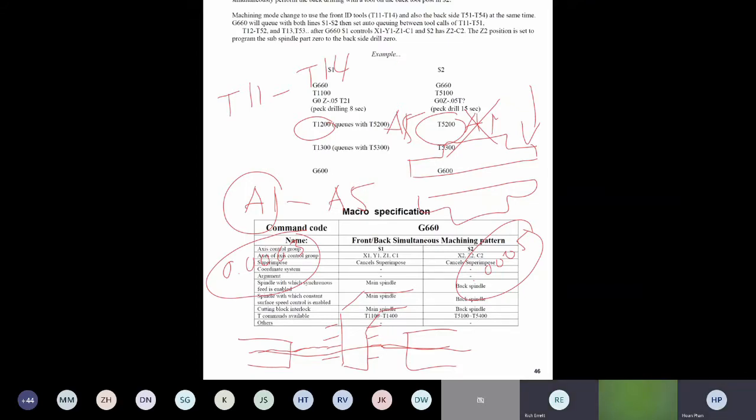So we have another question. Will the offset for tool 11 and tool 14 then affect tool 51 and 54? Yes, correct. So that's what I'm saying right now. The offset is whatever you use to adjust the main spindle tool in order to line up with the main spindle. So when you're using the A argument, either A1 or A5, you pick which side you want to have the tool centered with that spindle. So all the offset and geometry will also affect the other side too.